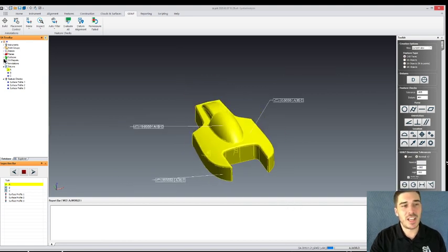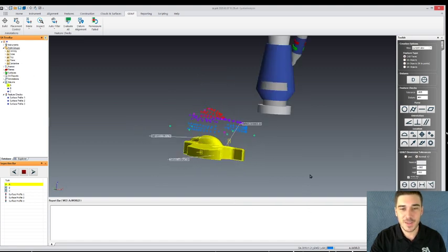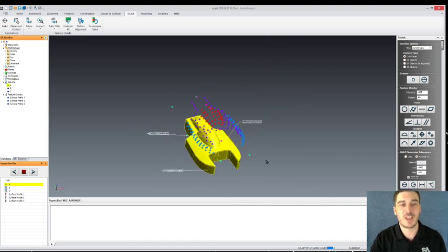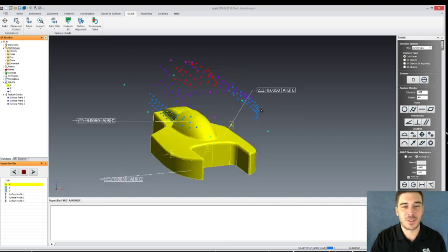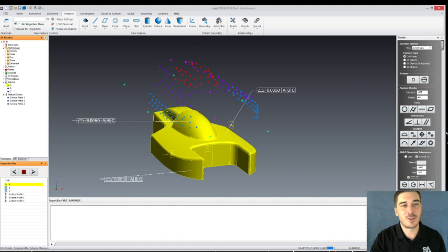In this case, we already have data, but unfortunately our data is not aligned to our part. So I'm just going to create a real quick relationship alignment to this data so that we can use that really handy auto filter function to auto filter all this data to those CAD faces. So I'm going to go to our Features tab, which is where the Groups to Objects relationship is.